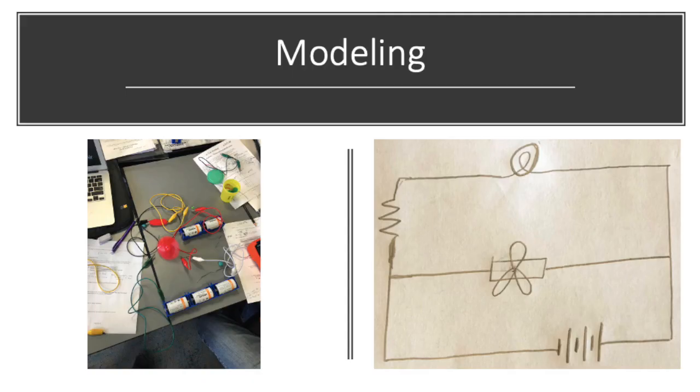On the left, we can see our fully functioning circuit with the fan and the LED bulb. On the right, we see a paper diagram of this. There are 3 1.5-volt batteries, pushing the current towards the light bulb. Some of the current splits at the first junction and goes into the current-limited motor, allowing it to run, while the rest of the current flows through the resistor, causing a voltage drop that fits within the voltage-limited capacity of the light bulb.